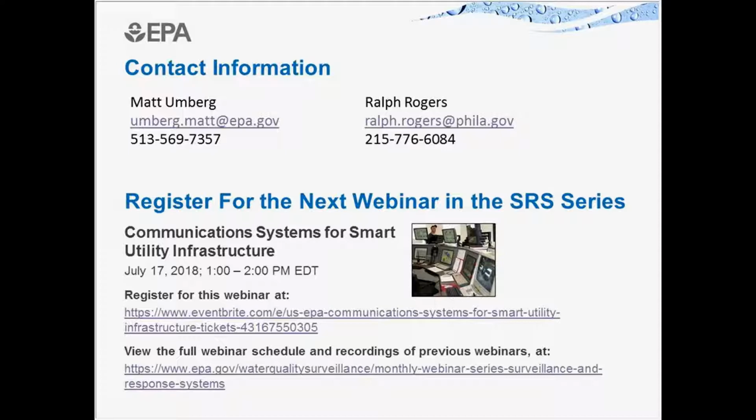Okay, thanks. The next question, what kind of platform do you use to interface GIS data with SCADA, and what SCADA systems do you use? As far as GIS, that's further down the data stream, more on the dashboard side. The SCADA software that we're using is called ClearSCADA, manufactured by Schneider Electric, and that's the DNP3-based protocol that we're using.